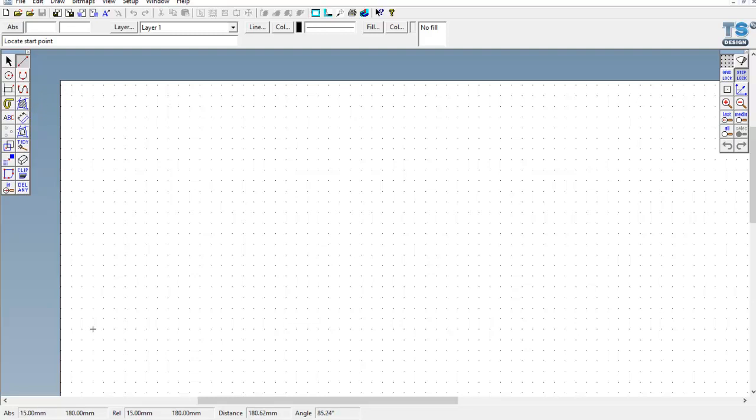35mm by 90mm down. So I'm going to click onto grid lock, and you can see at the moment the cursor is going in between the dots. It's not jumping to the dots. If I click the grid lock on, now it will jump from dot to dot, or grid to grid. So I know that every time I join one line to another, that's 5mm.